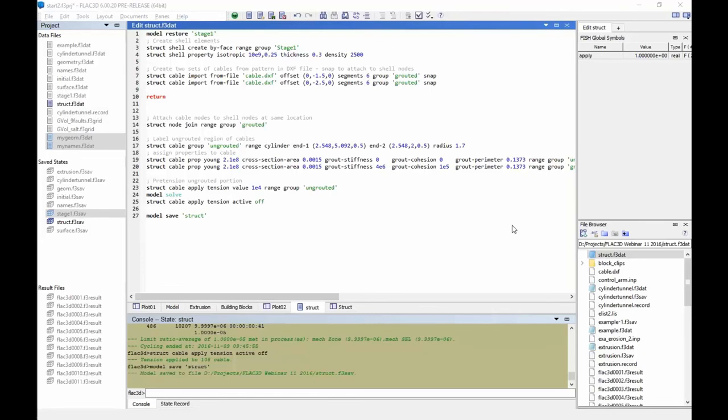Most times we build a model with the edges parallel to the axis. Can we rotate the model? Yes, that's actually easier now than it was before because most of the commands have the ability to specify an arbitrary local system, including the apply logic, which will automatically rotate to the face normal. And the zone initialize commands allow you to rotate your stress state. So yes, you can do that if you want. It's still probably better not to use a system that's different than your mining system. There are a number of reasons why in general that's not a good idea. But if you need to, you can.